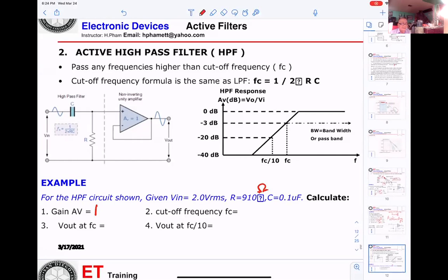You can use any inverting, non-inverting, or follower, depending on the purpose of the filter design. Engineers can use either one. Another advantage is that in this configuration, the op amp doesn't load the RC circuit, so it doesn't change the frequency response.